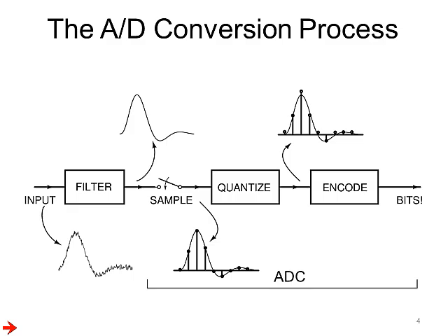This results in a discrete time signal, and then quantized, which results in a signal with discrete amplitude levels. These levels can therefore be encoded with a finite number of bits. So when one says an A to D converter, one is basically referring to this whole gamut of operations: sampling, quantization, and encoding.